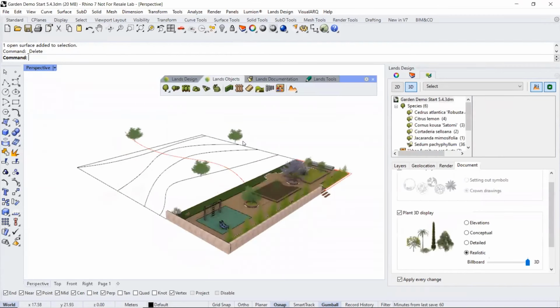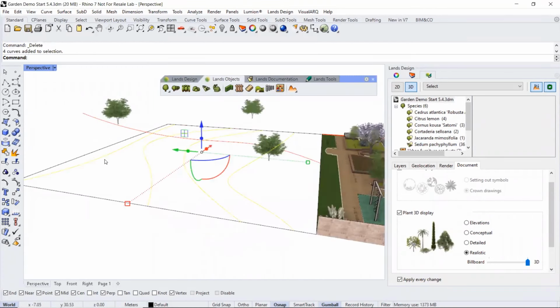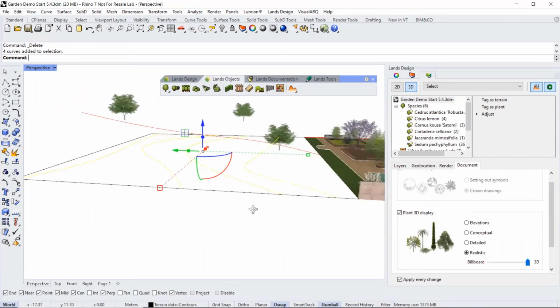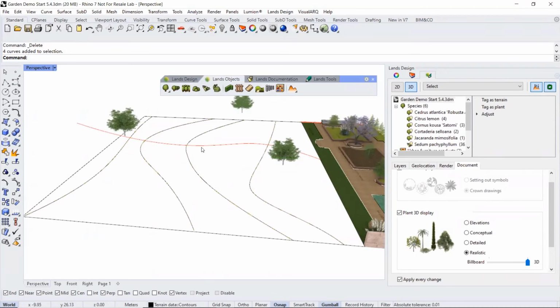There are different ways to create terrains. We have seen how we can import them from the web. In addition, we can create them from digital elevation modeling files. But also in a typical scenario, we will get a DWG with all the contours of the topography, and in some cases even in a flat position. So we will need to elevate first these curves in order to later on create a terrain.